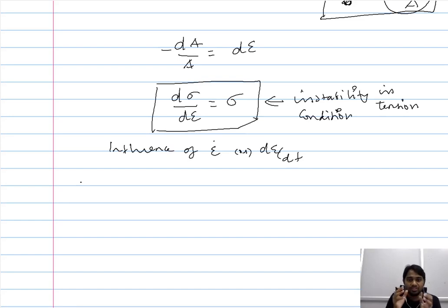So therefore, instead of governing the whole tensile test based on the stress, the whole tensile test is planned based on the rate of strain, or the strain that we impose on the system. So when you construct a tensile test that is based on strain, no matter whatever geometrical change the specimen experiences, you get the representative stress strain curve.